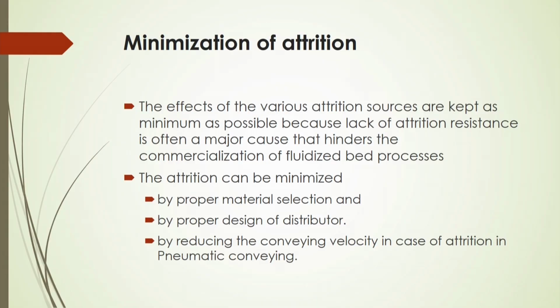Effects of the various attrition sources are kept as minimum as possible, because the lack of attrition resistance is often a major cause that hinders the commercialization of fluidized beds for particular processes. Attrition can be minimized by proper material selection, by proper design of the distributor, and by reducing the conveying velocity in case of attrition in pneumatic conveying. So, there are several options there. Of course, all those options have some